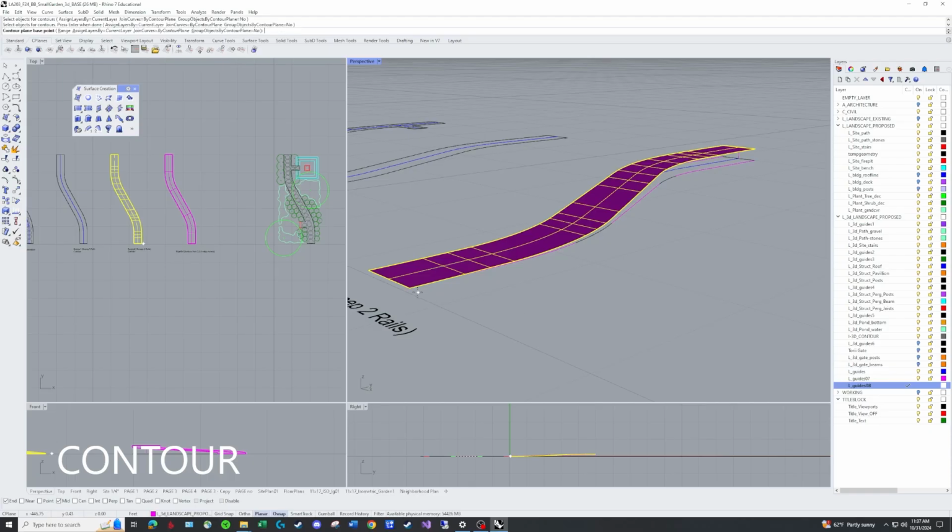So what I'm going to do is, the contour command is just type contour. Sorry, I'll do this one more time. Type contour, select the object I want to run contours on, enter. I just need a base point. I'm just going to choose this 0 point, and then it asks direction perpendicular to contour plane. So I want to run what we'd associate with a plan view or topographic map. So I want them to be vertical for this one.